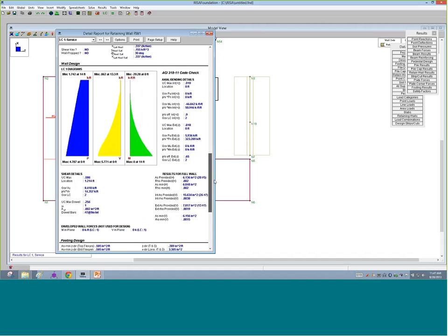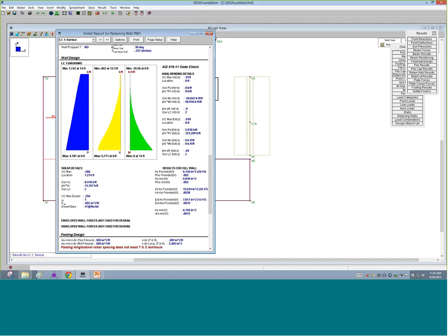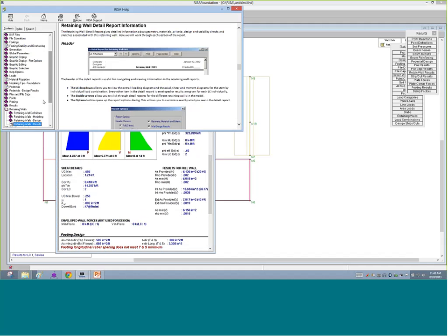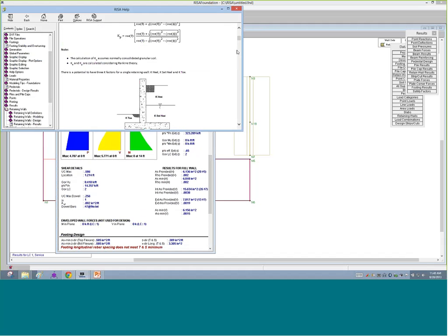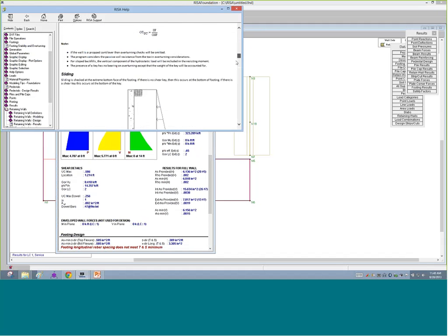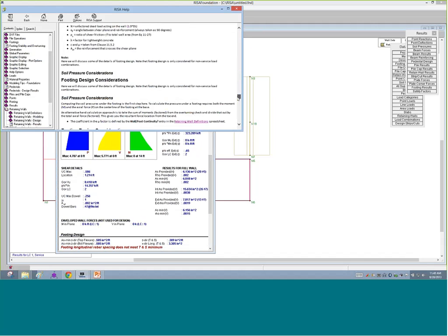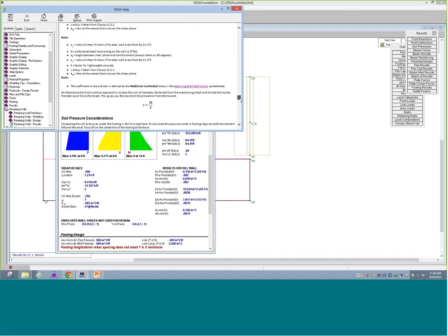And as you scroll down below that, we get to see some of the information inside of that wall. So you see the axial loads here, the shear, and the moment, as well as the code check information. Because we're using interior and exterior, it's going to be broken down separately. So you see that you have interior moment versus your exterior moment listed here. Now, one piece is there is a threshold. I always like to point this out because it's a piece of the code that, if you're not familiar with, you forget what happens here. So I'm going to point out this little piece here.